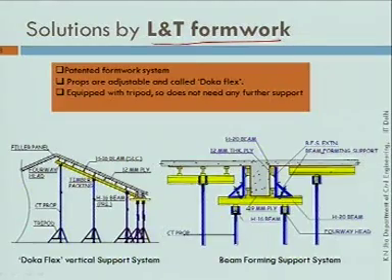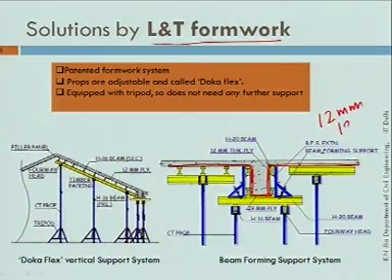You are already familiar with some of its component. What they do is they use this plywood. So here you have this plywood both for slab as well as for beams. The usual thickness of plywood is 12 mm or 19 millimeter depending on your design.